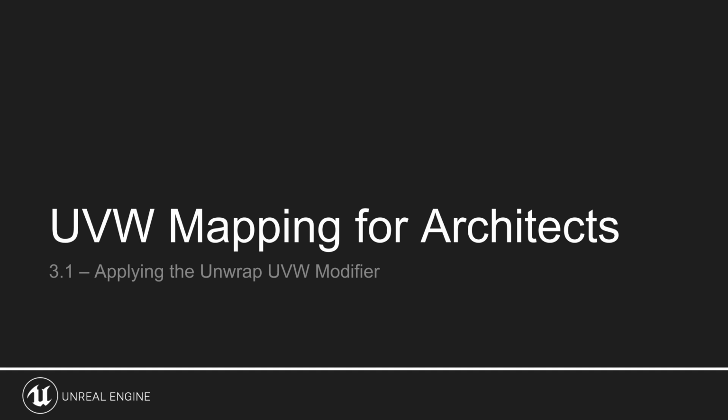The only way to really control how and where our UV maps and coordinates are placed on a static mesh is to flatten out the UVs and then carefully craft the placement of them. For this reason, the Unwrap UVW modifier can in many ways be described as the most powerful and versatile part of 3ds Max's UVW mapping toolset, with a similar option existing in all DCC applications that can perform UVW mapping.